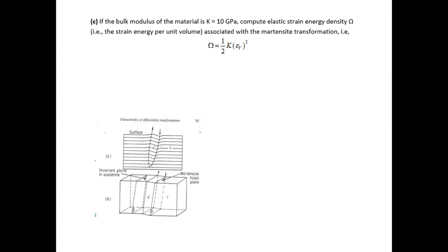So basically this means that, okay, thermodynamically I do want to do the transformation because it's going to reduce my thermal free energy. But on the other hand, there's no guarantee, and usually it's not possible, that the entire system is going to undergo the same transformation simultaneously. So I want to be able to convert the bulk of alpha to the bulk of beta.